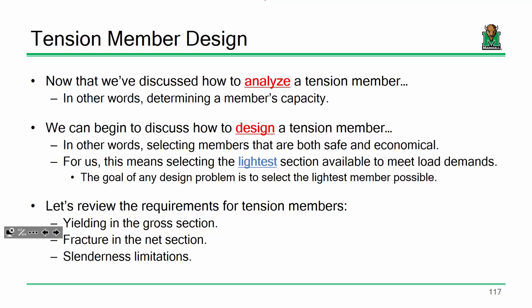Let's say somebody was designing the floor beams for this building, and there's hundreds of floor beams, and let's say they did the math, and every single floor beam in this building, you could use a W18 by 55. But there's that one floor beam over here that we could actually probably reduce to a W18 by 35. Probably just to keep the project simple, why don't we take this one and just bump it up to a W18 by 55? That way they're all the same. It's the same order, the same fabrication schedule. Ultimately, it's going to save time and money on the project.